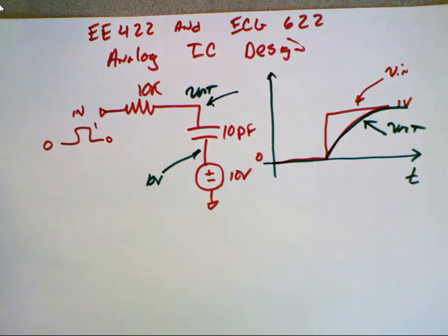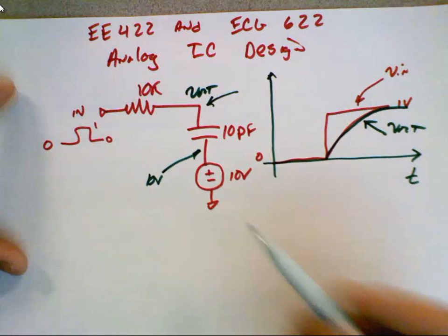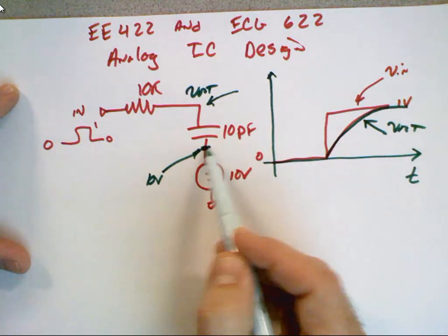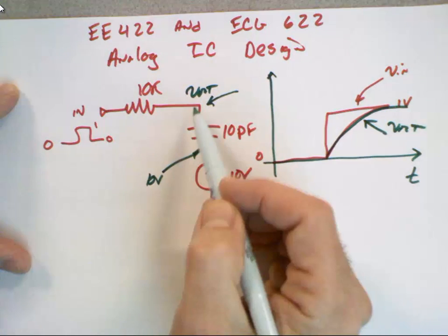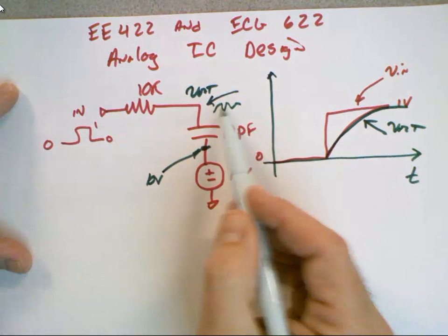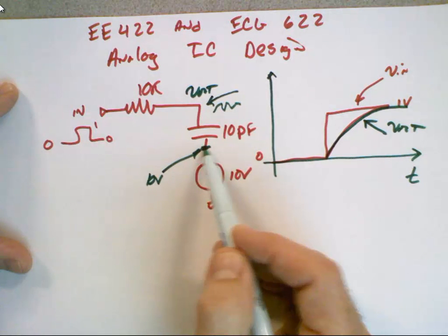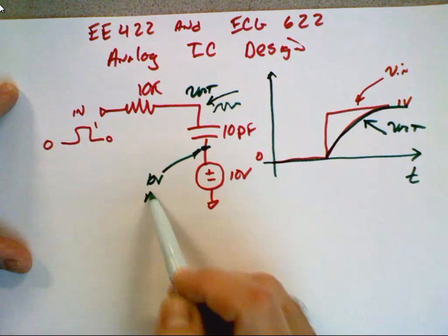So now, when you took electronics 1, and we said, this is AC ground, did you understand that? No? Okay, so this is at 10 volts and it's fixed at 10 volts. There's no way for me to vary that voltage, right? So it doesn't matter this thing's going up and down, or if it's a sine wave, or if it's a square pulse, or whatever. Nothing changes over here. This is AC ground.